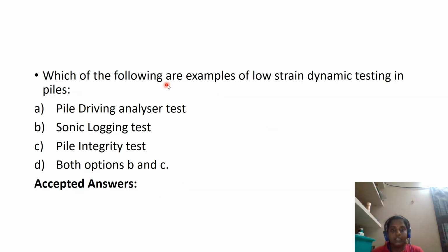Which of the following are examples of low strain dynamic test in pile? As I said, low strain dynamic tests are going to be of two types. That is going to be your sonic logging and pile integrity test. So the answer is going to be B and C.